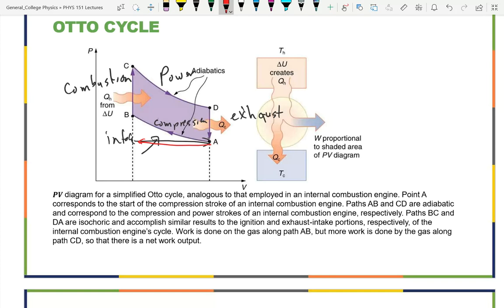But the octane is telling you about how quickly the gas burns. Longer chains take longer to burn. Shorter chains burn more quickly. If you have gas that burns too quickly, then you put a real hammer on the piston. And so you can have what we call pinging in a car. A car is pinging when the gas is burning too rapidly and hitting the piston so hard that it makes the piston actually rock, which, as you can imagine, is not good for your cylinders or pistons.